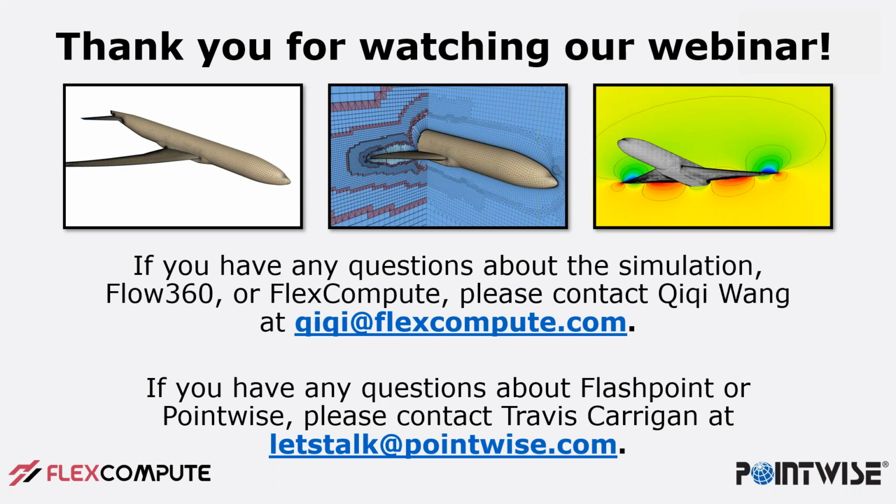Here's a good question. Let's see if I can maybe break this one up. The total drag totally matches Fun3D. My question is, what could be the underlying cause for the slight difference between Flow360 and Fun3D for the moment coefficient? Is it because each layer in the mesh is connected through an interface because of the nature of Flashpoint, or is it something else?